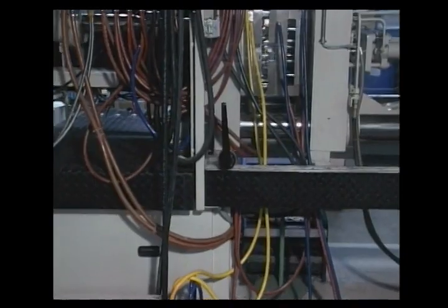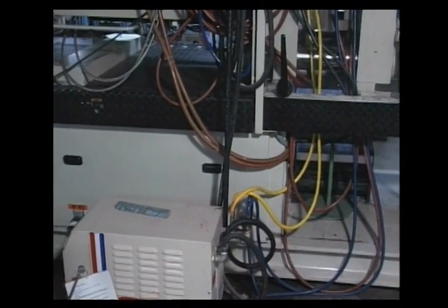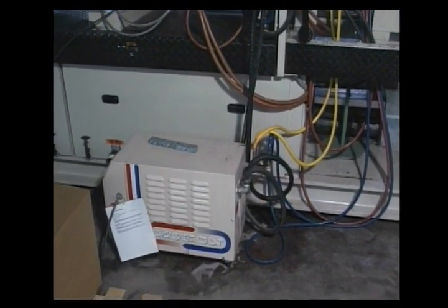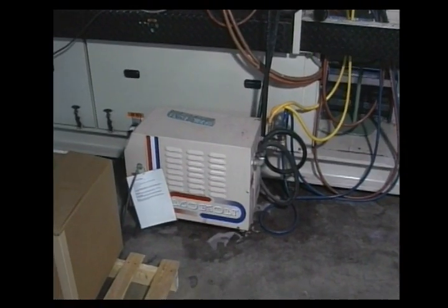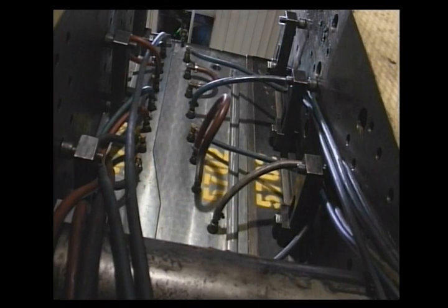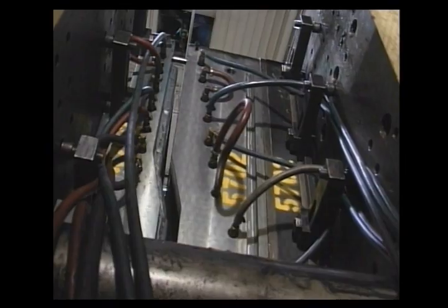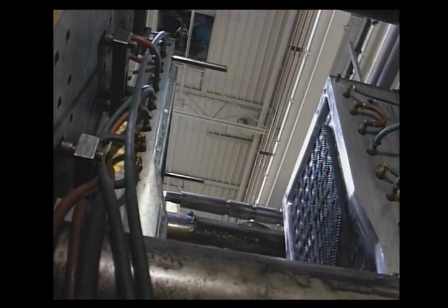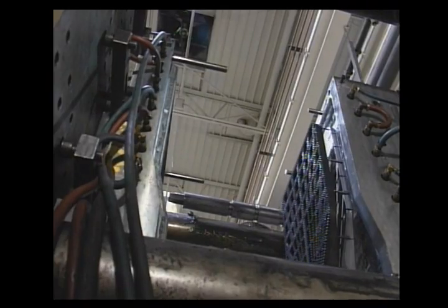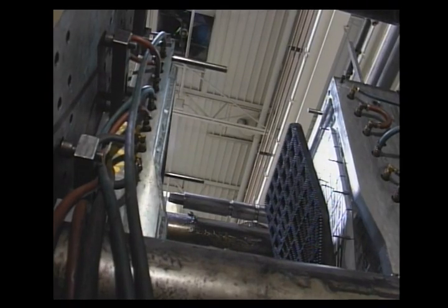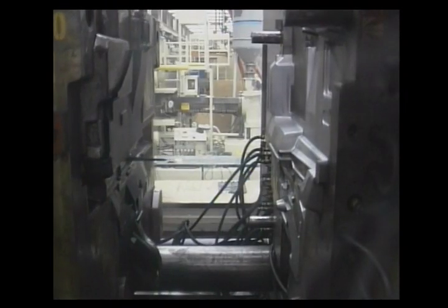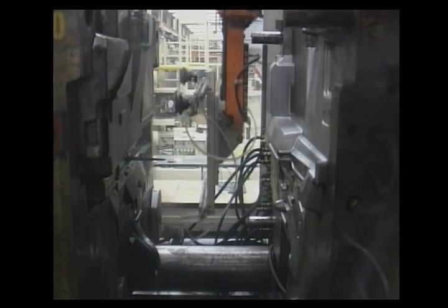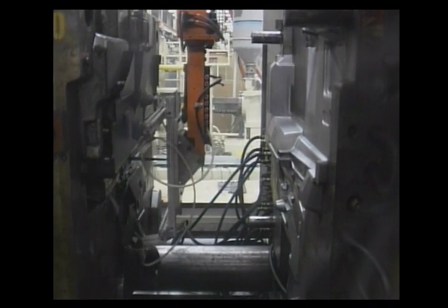Built into the mold are channels for circulating water, which is the mold's primary cooling medium. The water is pumped continuously through the mold to and from a cooling unit, removing the heat and solidifying the part. Proper cooling provides a consistent temperature and coolant flow rate, which contributes to controlled shrinkage, part strength, and other properties. The speed of the injection molding production cycle is controlled by the efficiency of this cooling system.